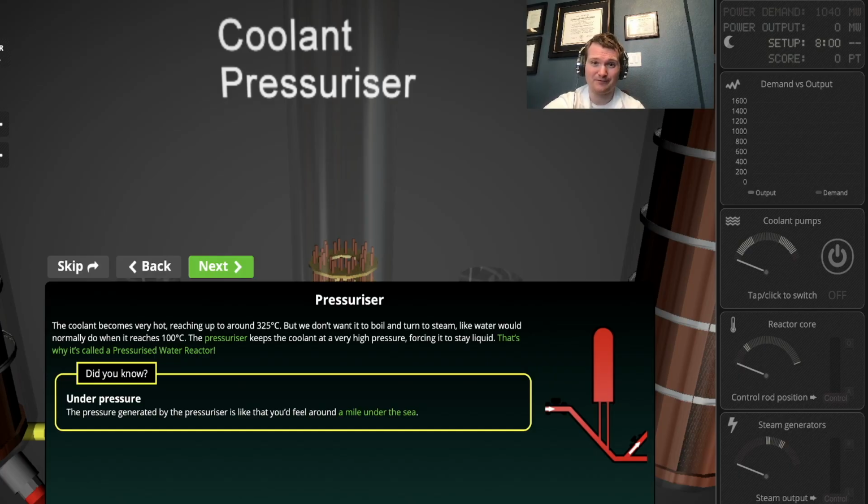Another way to improve efficiency is just when it gets cold outside naturally, because water gets taken in from a large reservoir, and that water is taken in and just goes to the condenser. Now, when I say the condenser, we're outside of the nuclear part of the plant and into the same steam generation part of the plant that exists in coal plants, natural gas plants, anything with a thermal cycle. But that's where your efficiency comes from, is that temperature difference between the steam generator and...